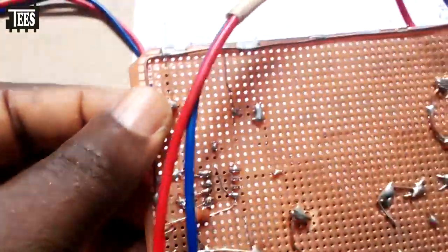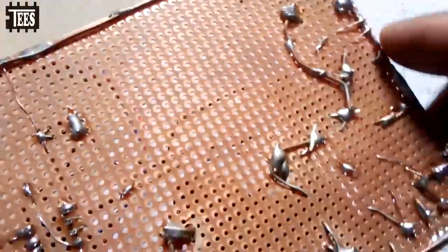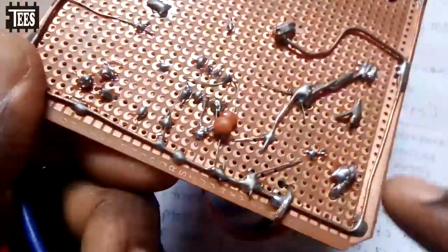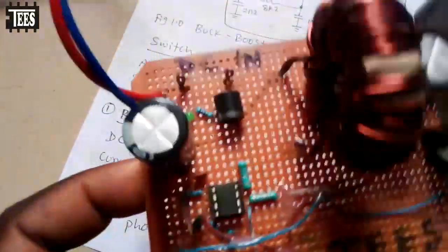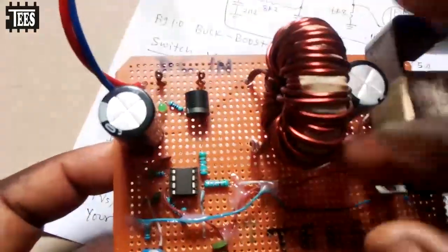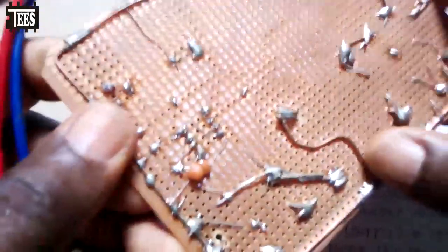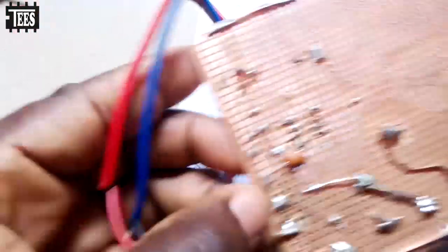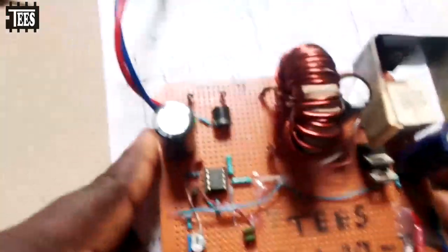If you look at the back, if you are constructing this thing, I use very thick copper wires here. That's for the ground terminals. You can see the thick copper wires I use. Very thick. Why? Because around this area, you're having high current. So in those areas, make sure your connections are very thick. With this, I don't have any issue.